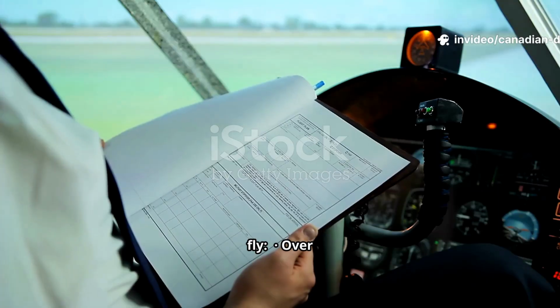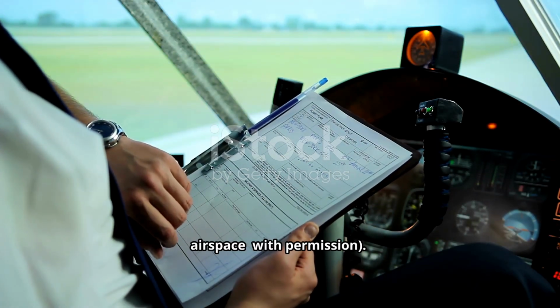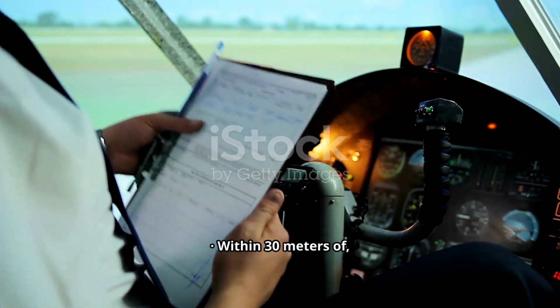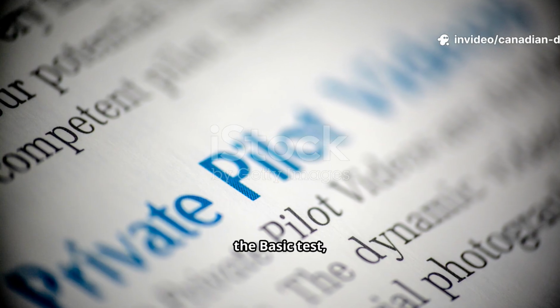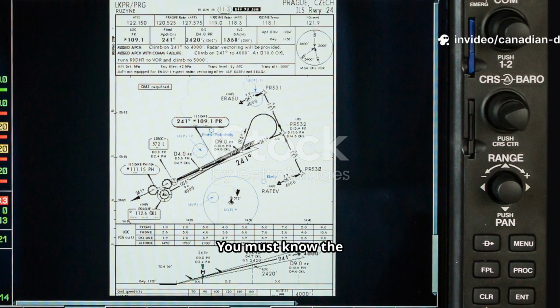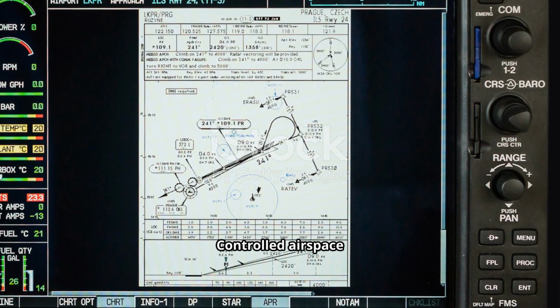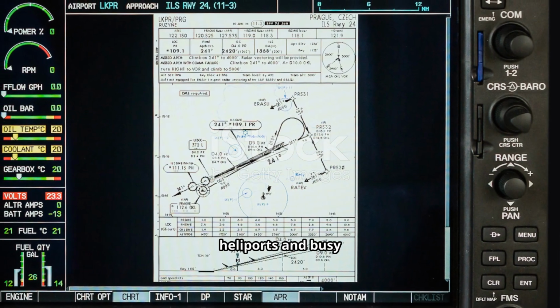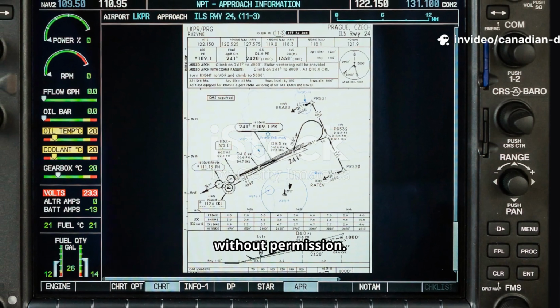This allows you to fly over bystanders, under specific conditions, in controlled airspace, with permission, within 30 meters of, but not over, bystanders. Since you're taking the basic test, you must know the limits of basic operations cold. You must know the difference between controlled and uncontrolled airspace. Controlled airspace exists around airports, heliports, and busy flight paths. Under basic operations, you cannot fly there without permission.